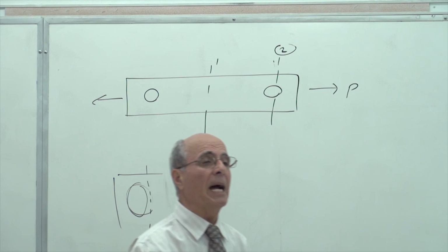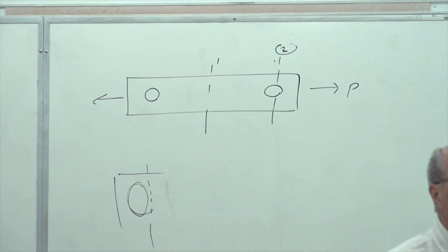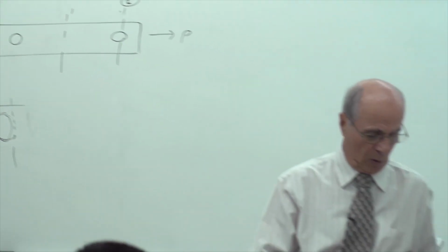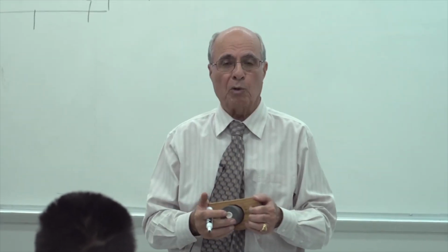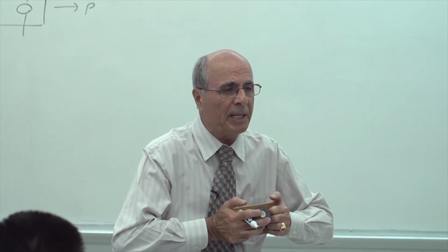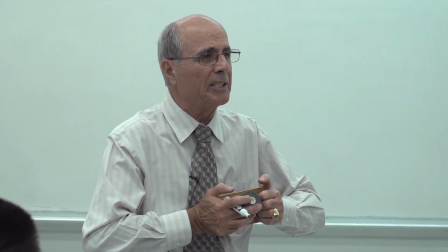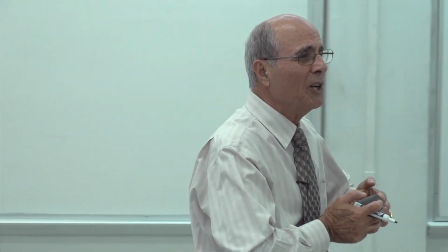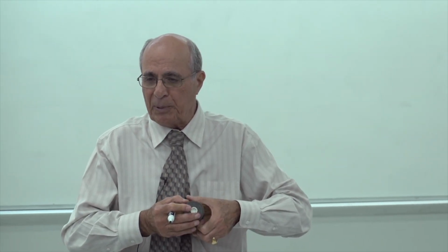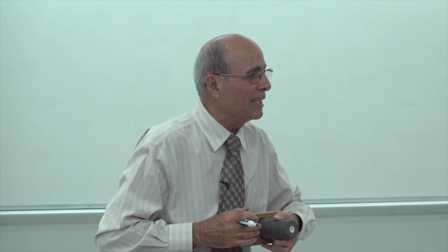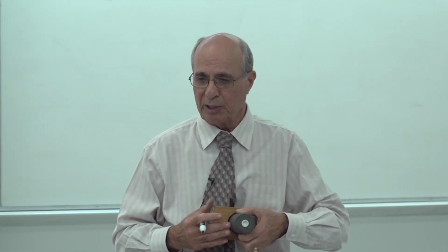But this will not happen in compression mode. In compression mode, when you put the rod under compression, this is going to grab the pin. Everybody understand? And the pin is as strong as wood, and it is in compression. There is no separation. In tension, they are separating from each other. In compression, it grabs the pin, and the pin is usually much stronger than this material. This is usually the case. So in that case, we do not need to subtract the hole.